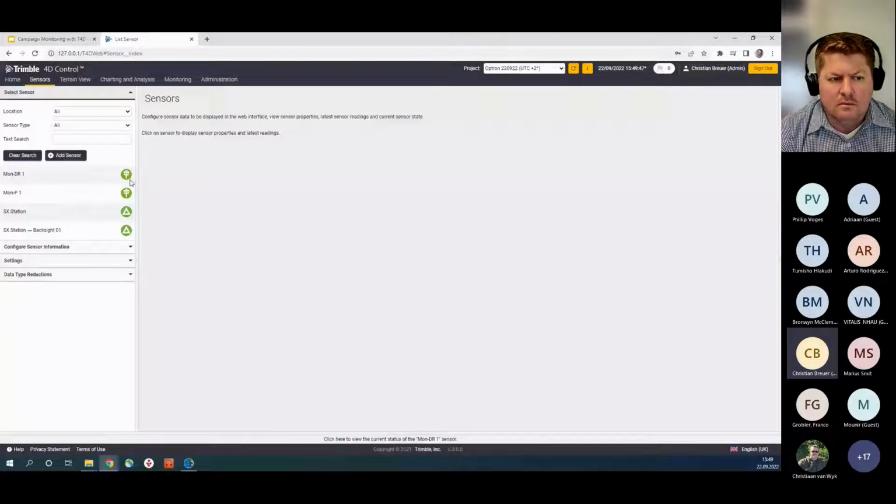These you can see is a prism icon for it, because this is my monitoring point. The backside point, of course, I don't monitor. But what I did is I select, okay, this I said this is a control point, but I still want to see the raw data when measuring to the backside point, because the backside point in the adjustment is fixed, so I will never see any movement for it. But if there is anything happen with that setup, I could see it by monitoring the raw data.